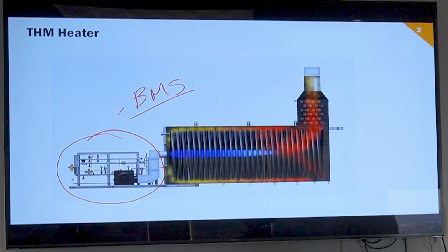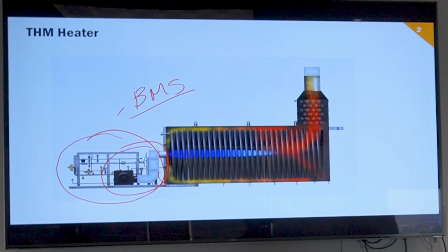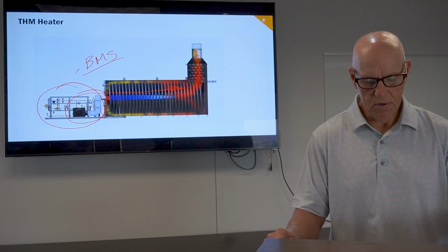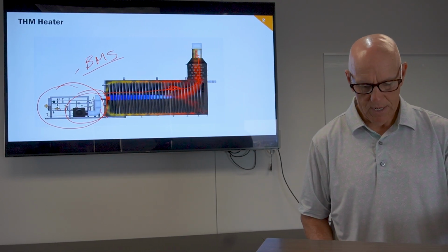Well, I can positively assure that with a forced draft blower. I can turn this blower on and I push all the air that's in this, and if there's any gas that has leaked through the system, I'm pushing it all out of this heater before I spark this pilot. So it's a great safety feature to have a forced draft operation.